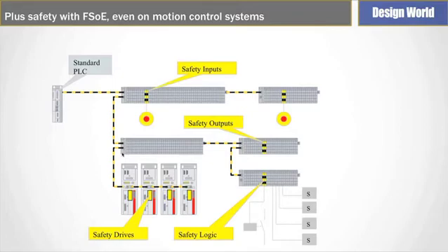And one of the advantages of a safety protocol such as this is the ability to have drives where we don't just drop the mains power and turn off the drive. Now we can actually command safe commands such as safe torque, safe direction, safe speed, and actually implement a logically safe implementation on a machine or a robot.